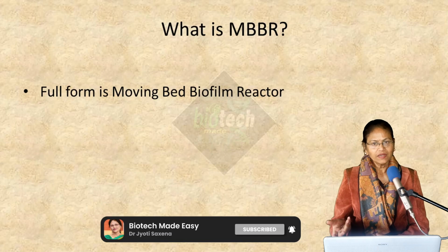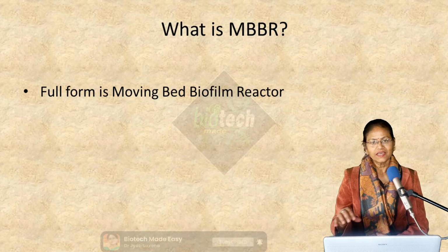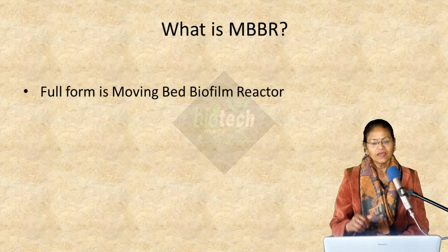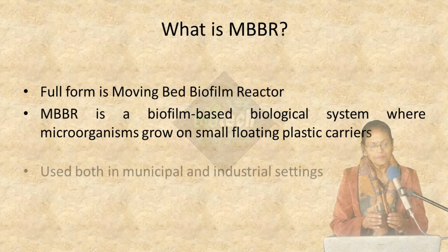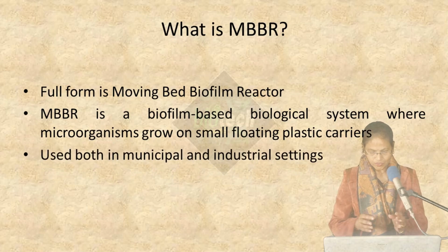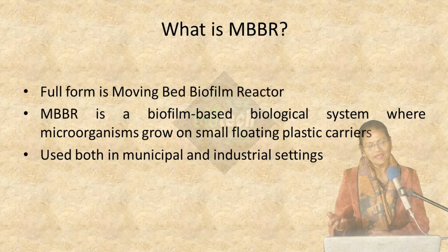MBBR is moving bed biofilm reactor. Here are the two keywords: moving bed. That means all the time the carriers which are present here are moving, and it has a biofilm. So this is a biofilm based biological system, and here the microorganisms grow on a small floating plastic carrier. We'll see what type of plastic carriers these are. They can be used both in municipal and industrial settings. That means for cities and towns they are good enough, and they can also be used in industries.